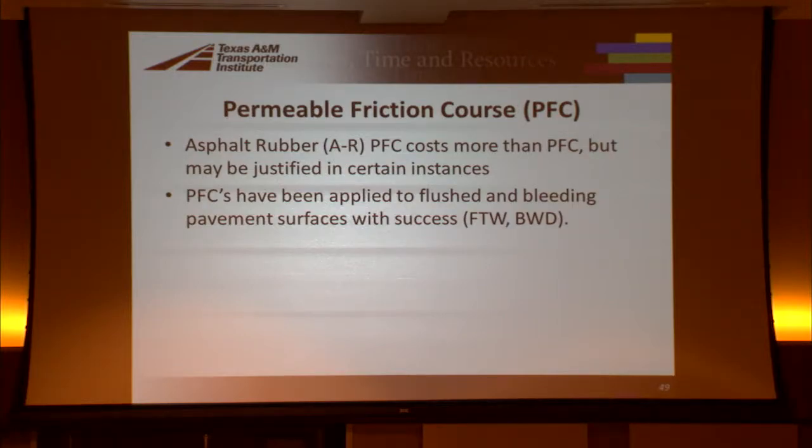Asphalt rubber PFC costs more than the regular PFCs, but may be justified in certain instances, especially for maintaining a low level of noise. In Fort Worth, we did the previous generation, what we call plant mix seal, but also porous friction courses. Mainly it started because we had a lot of flush and bleeding seal coats in the district, and actually the district went whole hog with doing it almost throughout the whole district.